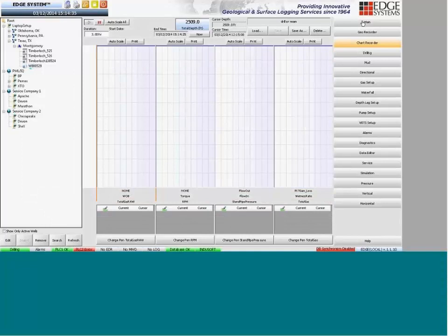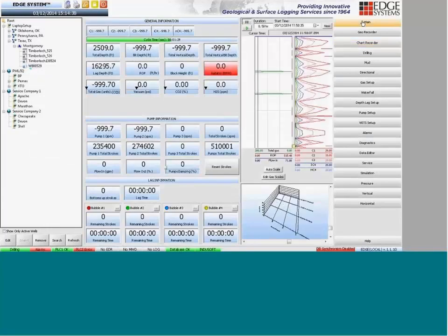The main screen itself has, again, this is a chromatograph chart. At the top we have chromatogram data, instant chromatogram data running across the top. Now this is simulated data, by the way, it's not real information, so my apologies if some of the numbers are a little unusual. And these little -997s are error codes, so we know we're not getting real data.